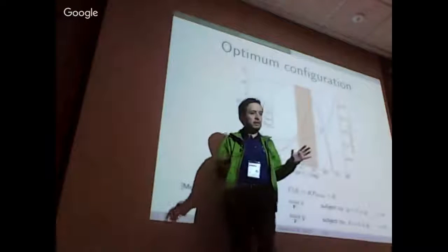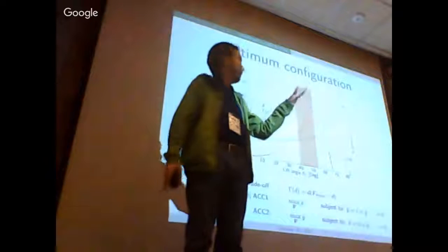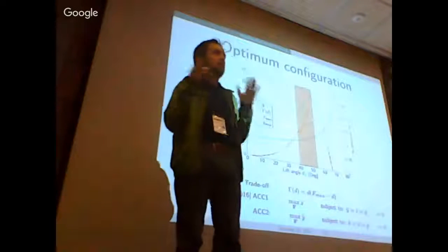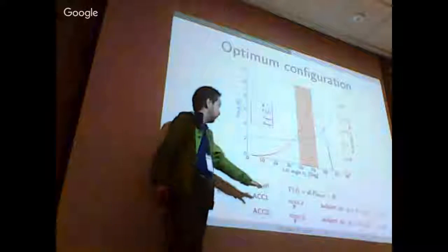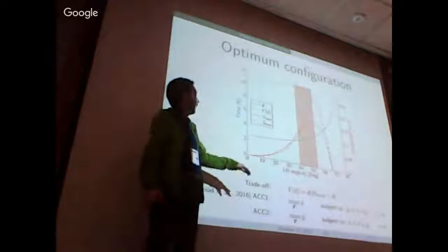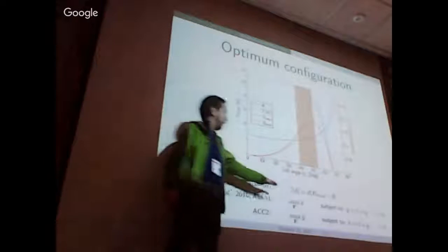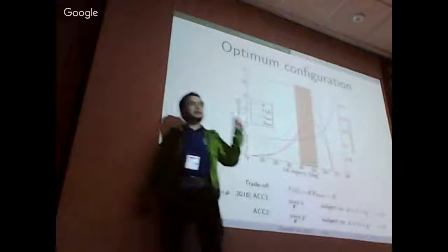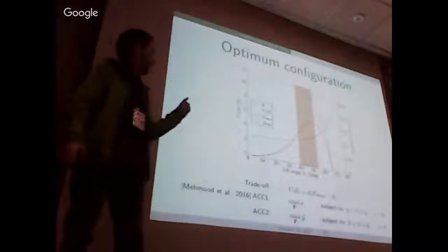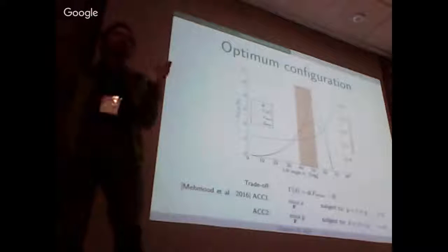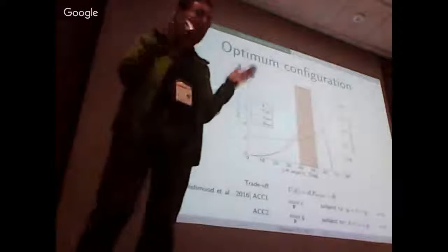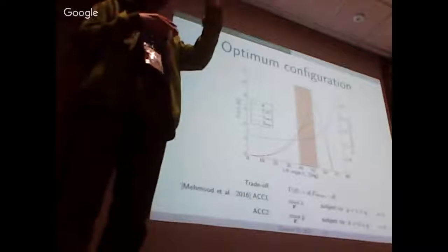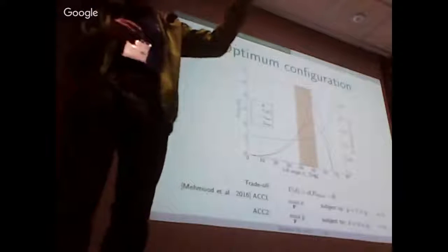So we chose a configuration for the vehicle which could help us increase the maximum acceleration over the x and y axis, and we propose a trade-off between the maximum force that every motor can exert and the margin that we have to counteract any force by just accelerating or decelerating the thrust force of the motor.